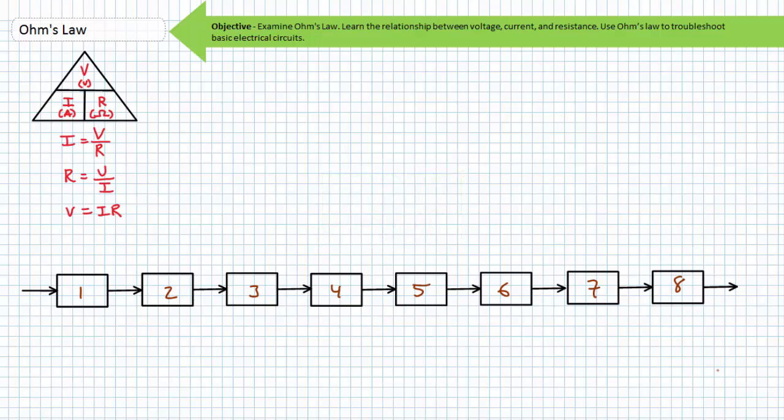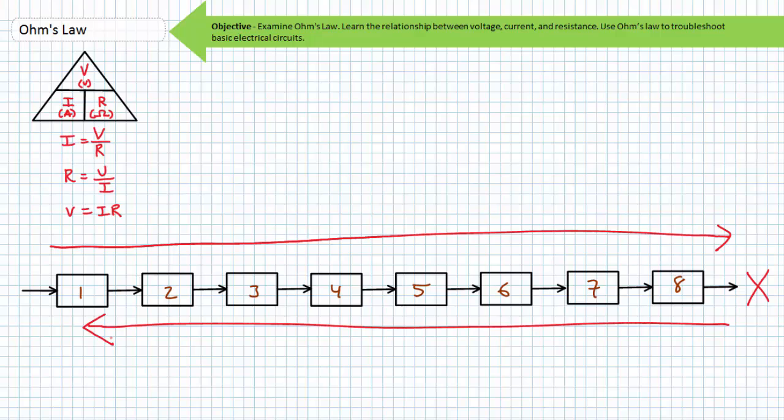Each substage's output feeds another substage's input. This same visualization can often be used to efficiently troubleshoot a malfunctioning system. If the end stage of a multi-stage system is not delivering a required output, where one starts troubleshooting is of critical importance. One might be led to believe that you have to start from the beginning and work all the way to the end, or vice versa, observing and recording all the way. This might work, but it is not the best use of your time.